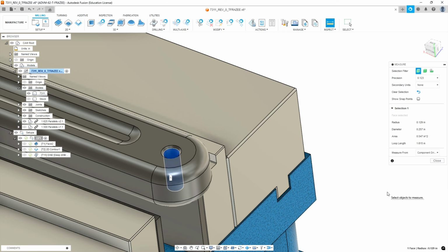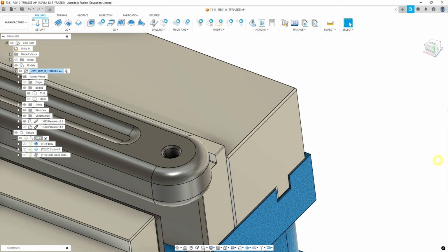So we're going to come in here with a 1/4 inch end mill after the fact and skim the walls of this to make it the right size. Not the most elegant solution, but that's what we're going to do. If we had a smaller end mill, that would be the preferred tool to use. So first we're going to drill it, but the hole will be undersized.